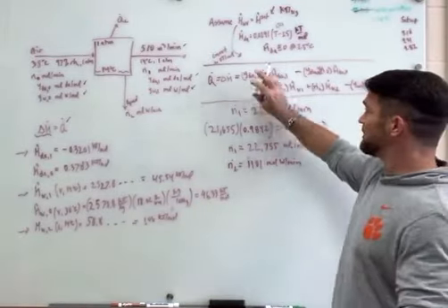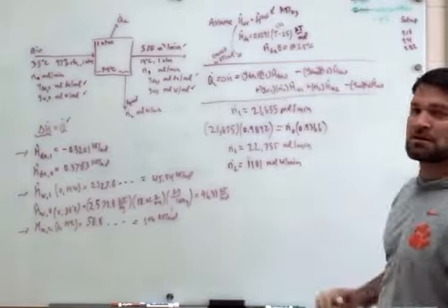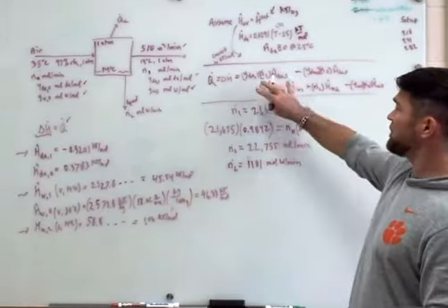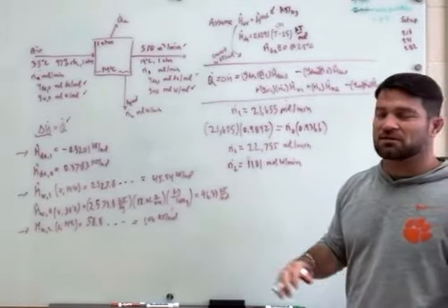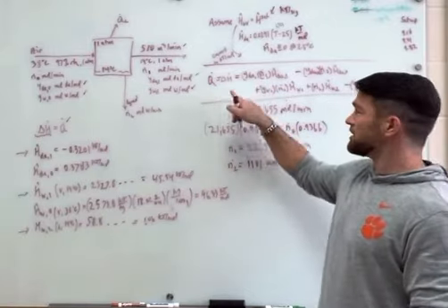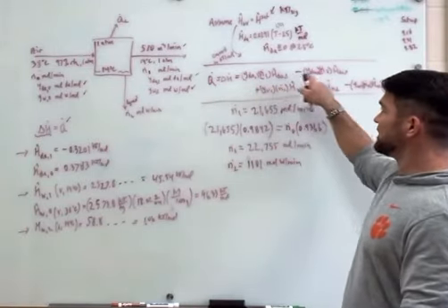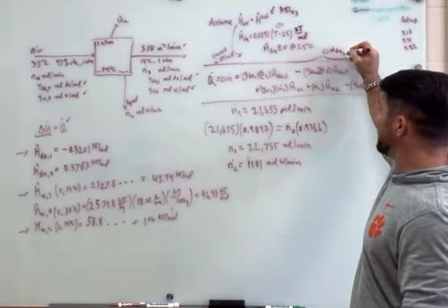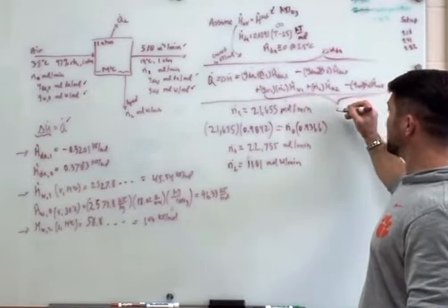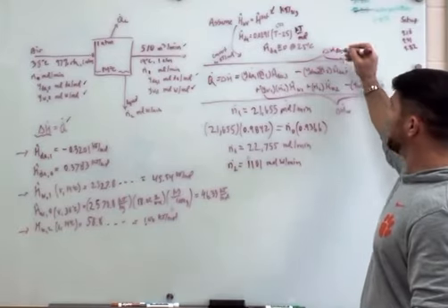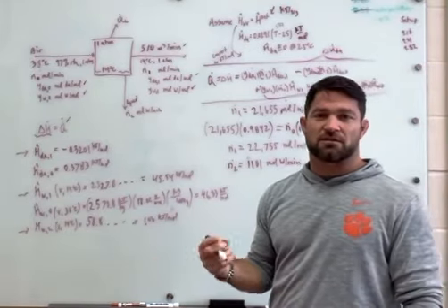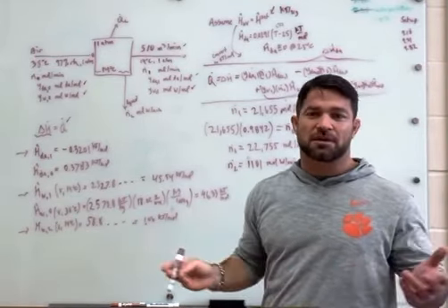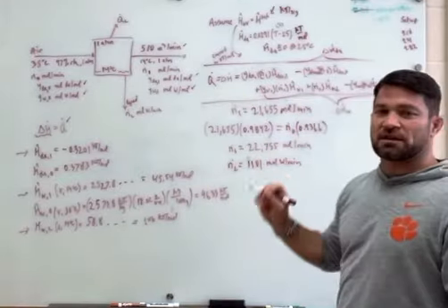So you can see I have the sum of what's coming out minus the things coming in. I wrote it this way just because the other way you can consider this is that this right here is just the delta H. These two things up here at the top are just delta H of the dry air, and then those on the bottom are delta H of the water. So the total delta H is that of the air and that of the water. Or you can split up species like that. You can do the calculation like this.